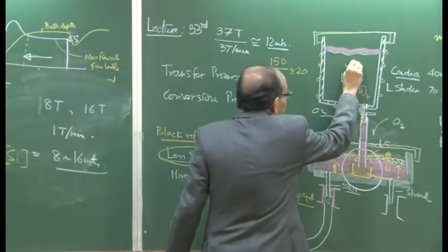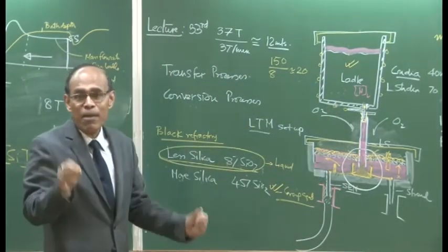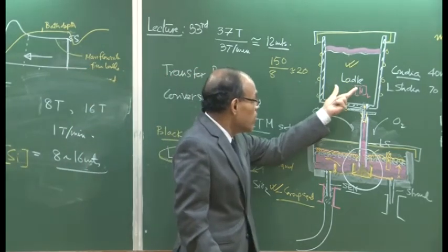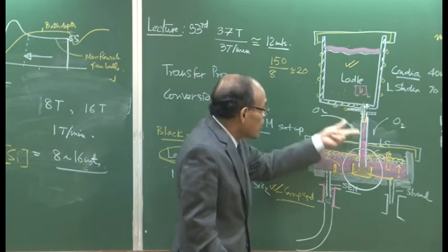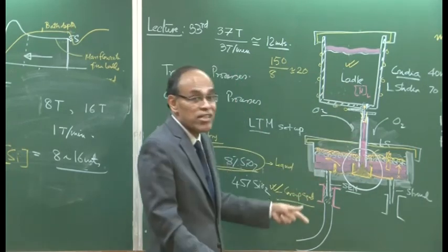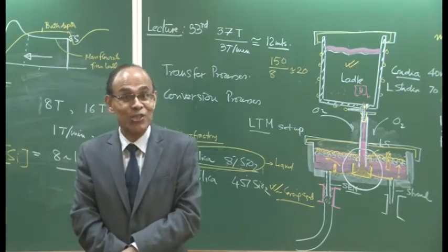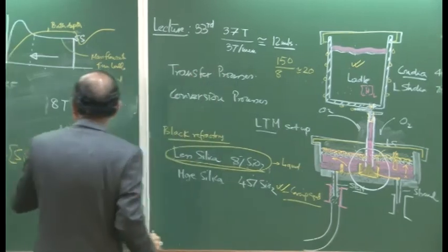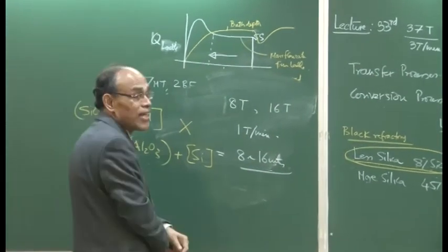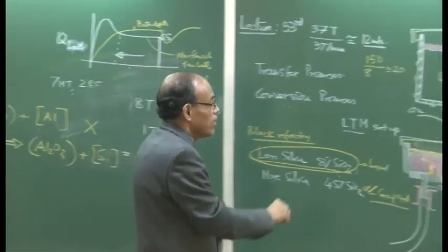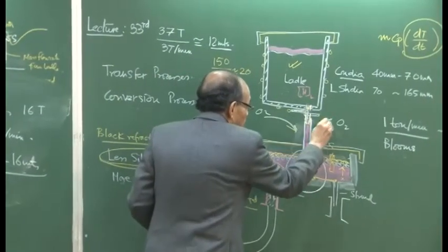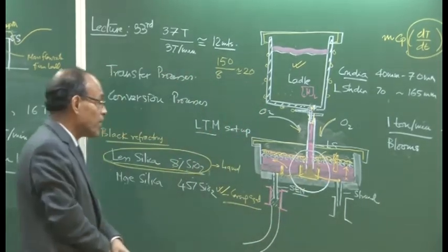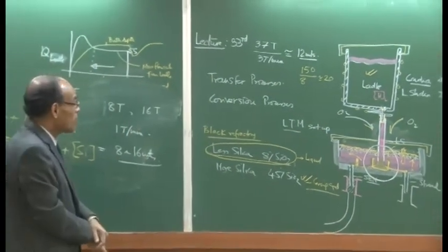The best quality of steel is sitting in the ladle, in terms of its cleanliness. I want to preserve that quality, and I must ensure that during the transfer process via a tundish, the quality of steel does not undergo any deterioration, and that is a big challenge to the steelmakers, and therefore, this reaction must be minimized at any cost in the tundish. So is the ingression of atmospheric air through the shroud joint, as well as air steel mixing in the tundish, and this must be stopped in any case.